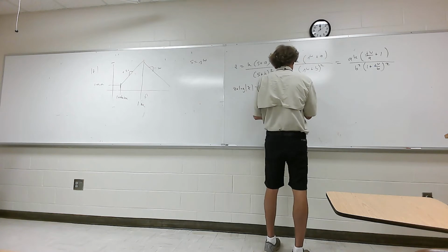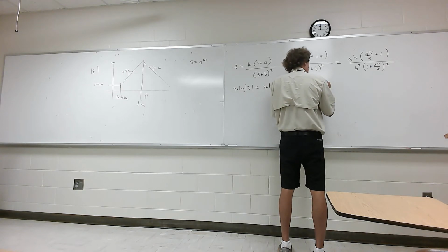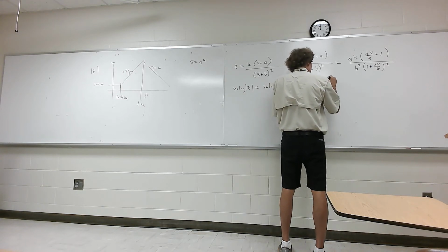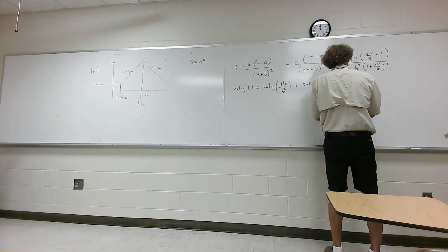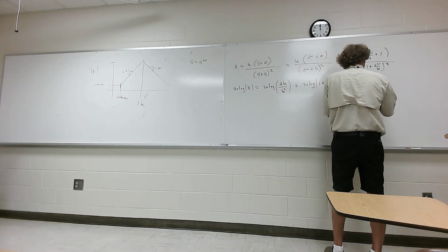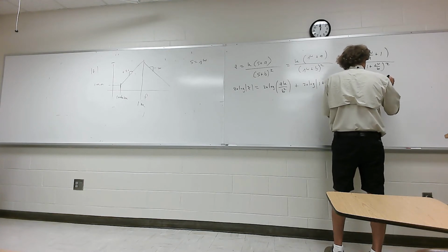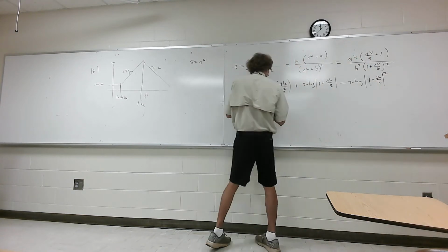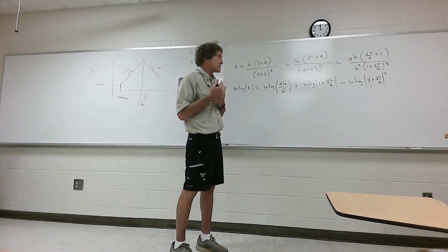Then it's going to be plus 20 times the log of simply the magnitude of 1 plus J omega over A. Then it's going to be minus 20 times the log of the magnitude of really 1 plus J omega over B, but this is squared, so I have to put squared. Now, the only thing I've done there is put it in terms of a Bode plot form. Y'all follow me? We're going to talk about the poles and zeros in a second.